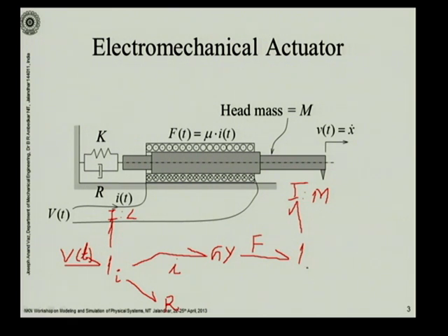So now we are on the velocity of this head mass, but we still have to model this spring and the damper. So what should we do? We can say that the housing is fixed. So we'll fix it with the help of a source of flow which is equal to 0.